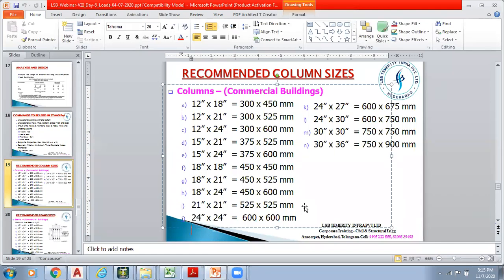Compare these two. The reaction that we are getting in STAAD would be nothing but the load, and these are the capacity of columns. So based on the reaction that we are getting, we will compare with the capacity of column, and then we group them separately.